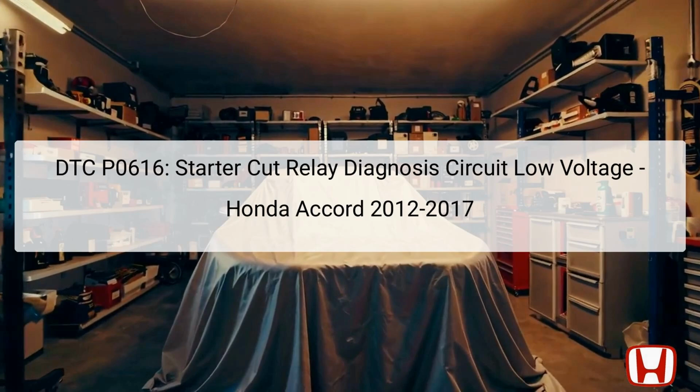DTC P0616 refers to a malfunction in the starter cut relay diagnosis circuit, which affects the Honda Accord models from 2012 to 2017. The starter control system plays a crucial role in preventing the starter from accidentally engaging when the vehicle is not in proper conditions, such as when the shift lever is not in the park or neutral positions for continuously variable transmission (CVT) models, or when the clutch pedal is not depressed in manual transmission (MT) models.